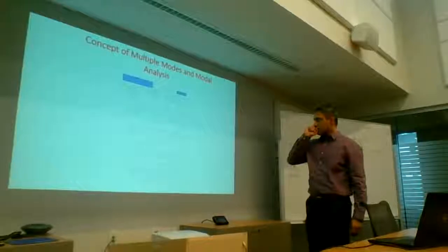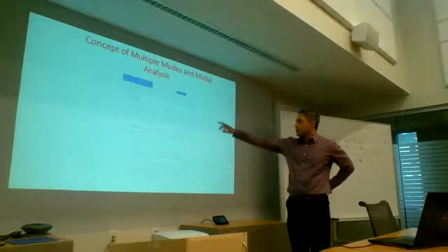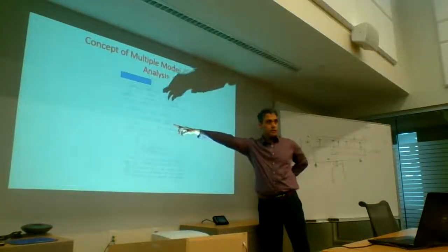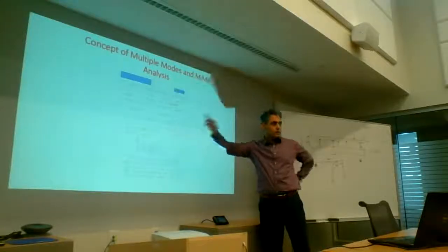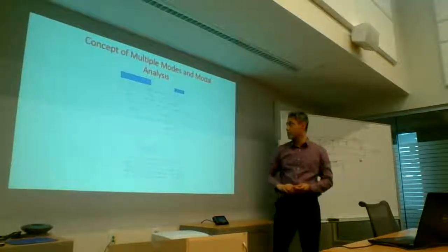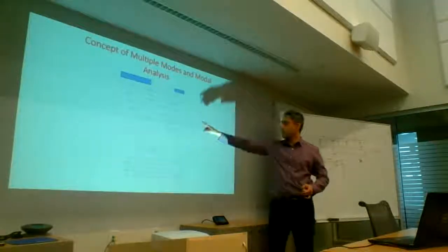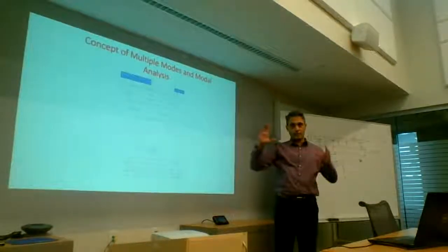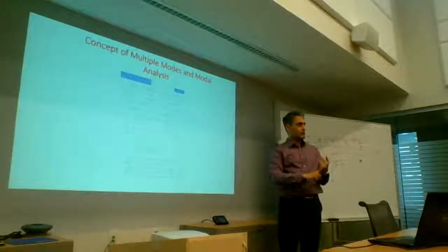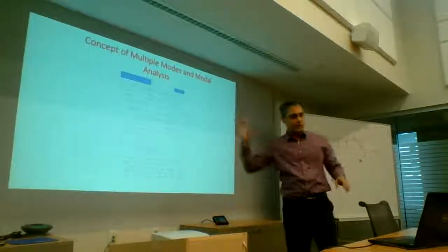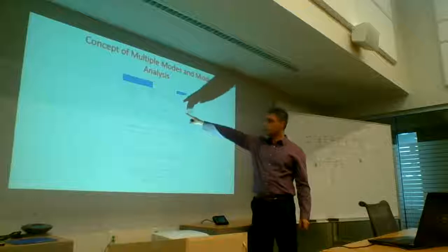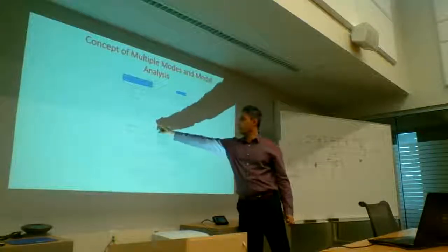So to get the, this is now in modal coordinates. This is not in use, okay? Now you've decoupled it, but now you're working in a transformed system. You're working in the modal coordinate system. And so what you need to do is, again, you need to solve that equation of motion, but it's a single degree of freedom system. So you can solve it whether you use time history analysis or you use a response spectrum, whatever, you can solve that separately.